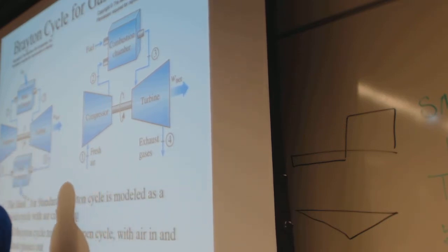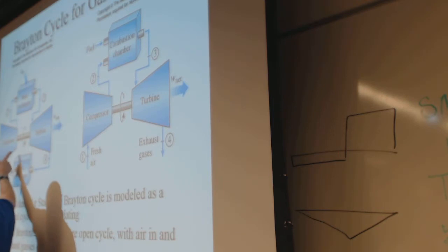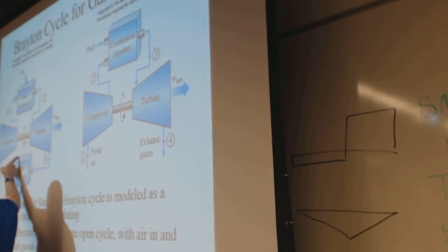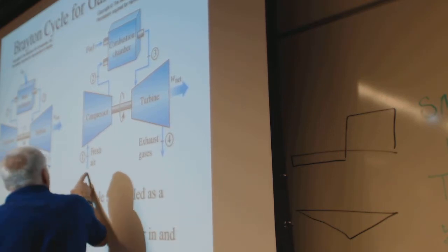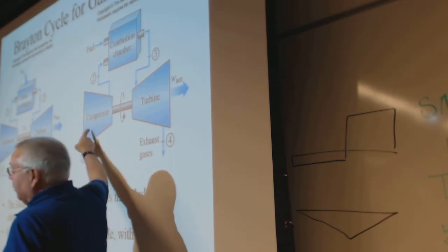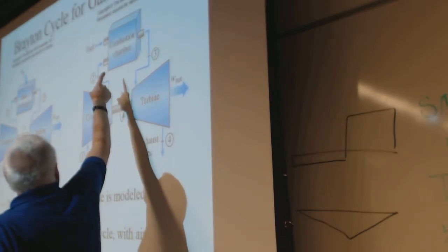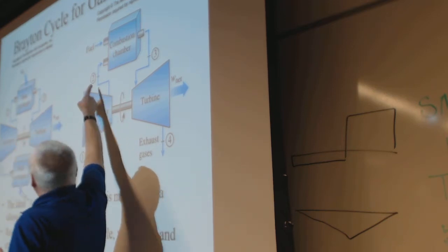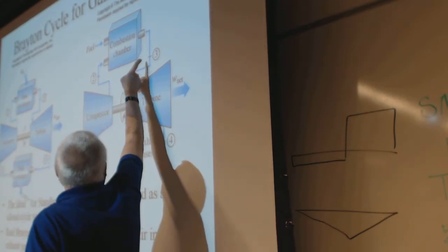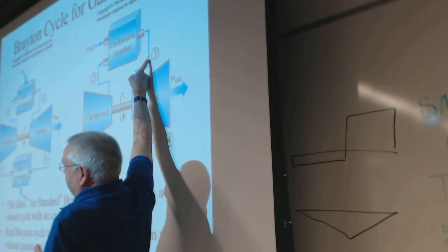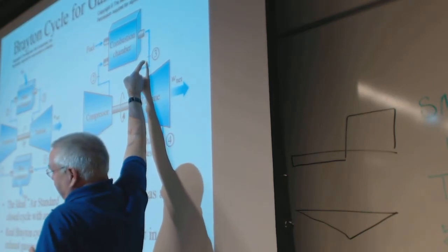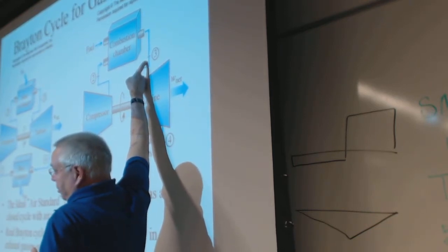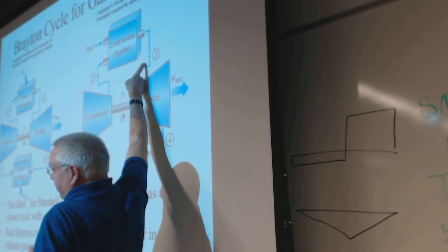Now, at 30,000 feet on the wing of a 747, that's not how it works. At 30,000 feet, the air comes in through the nozzle. It does have a compressor. It does have a combustion chamber adding heat. What you do is you add fuel. What comes in is air, and what comes out is air plus fuel combustion products, which would be CO2 and H2O.